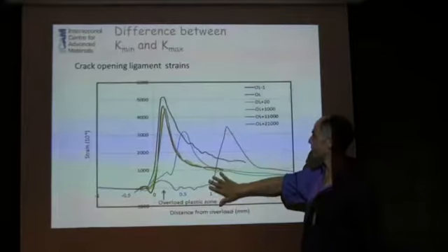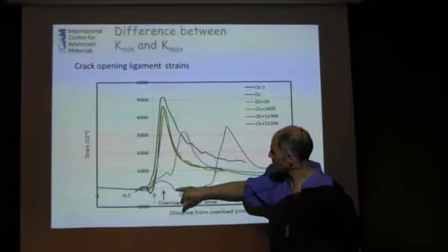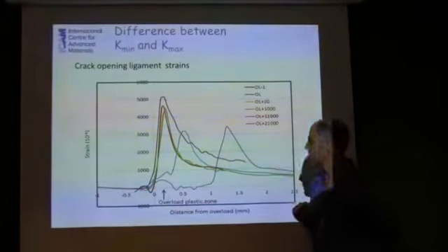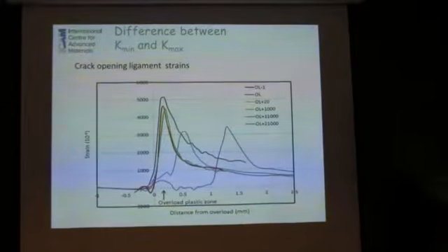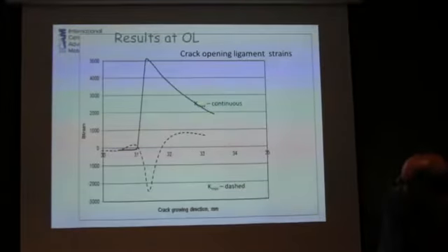When you go further from the crack, you do start to see differences in the elastic reload curve, largely because of the effect of the overload phase contact. So as the crack grows, you can see largely elastic behavior, but with some extra changes.